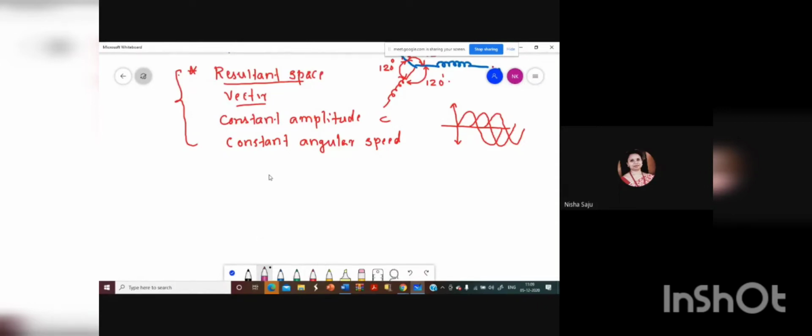So this SVM treats the sinusoidal voltage as a constant amplitude vector. You have to be very careful here, because it will have a constant amplitude and it will be rotating at constant angular frequency. This SVM modulation technique mainly calculates the duty cycles of the switches, in order to get the desired output voltage on an average basis without the use of a carrier waveform.